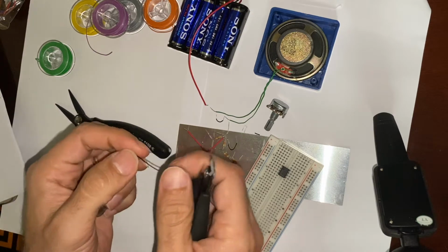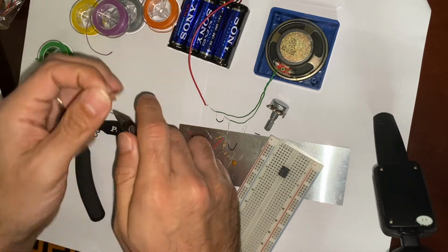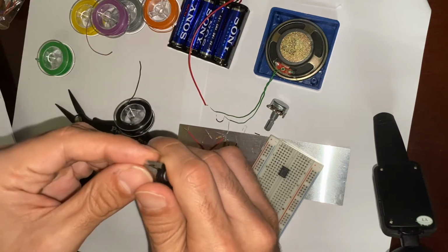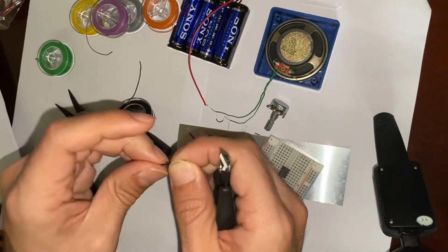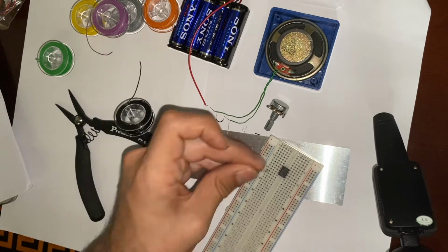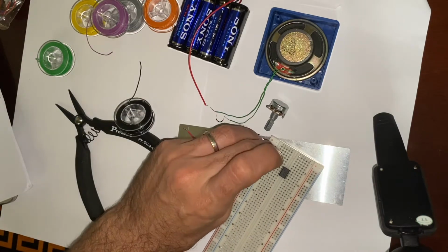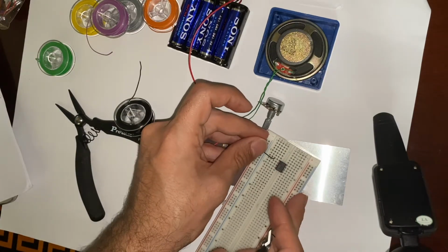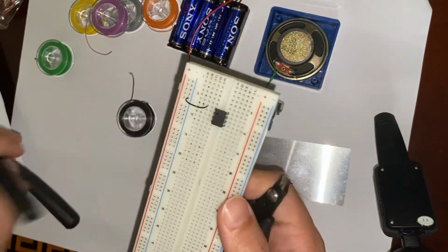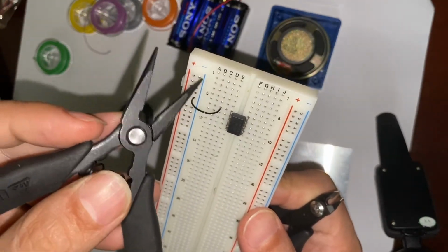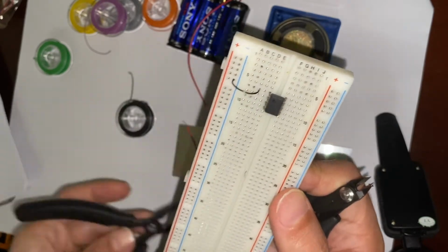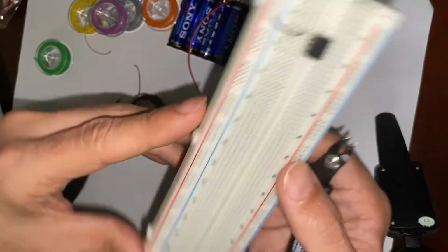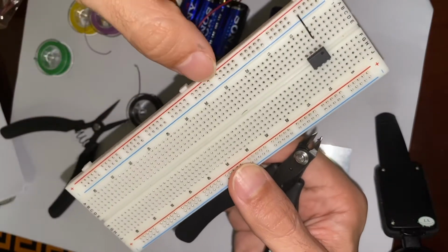So I'm going to use a black color for the cables I use for ground. That is essential in my way of working. I understand that other people don't have that habit, but actually we peel off a little bit of the cable, we insert on the blue line or black line that you have on each of the power rails, and that way we know everything is connected there is ground. And I also make it very clear, because I use black color, that that's going to be the ground.